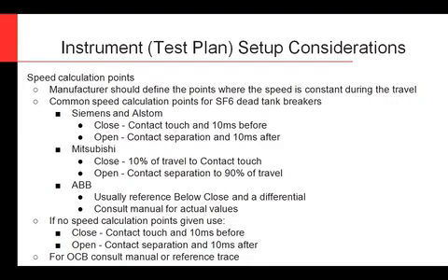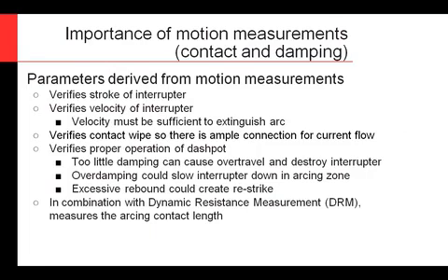Oil circuit breakers, they generally would give you some reference in the manual, or you'll see an old test result, and those generally are a lot longer. They're not as much in the arcing zone. They almost go over more the total travel length of that circuit breaker. But if you don't know and have no reference, I generally go with the contact touch in 10 milliseconds before, and this is what IEC recommends. And really this has to do with it's a half wave. In the IEC world, we generally have 50 hertz, and so 10 milliseconds is 1/2 cycle there.